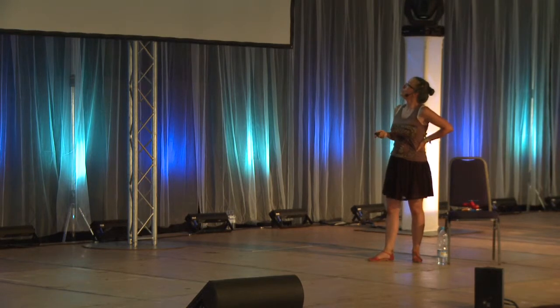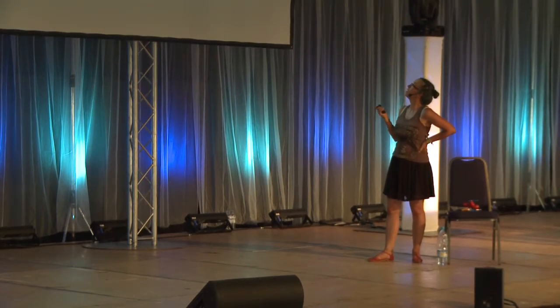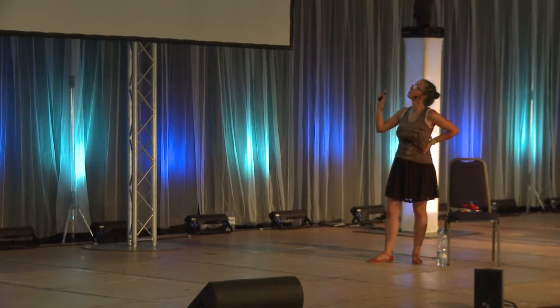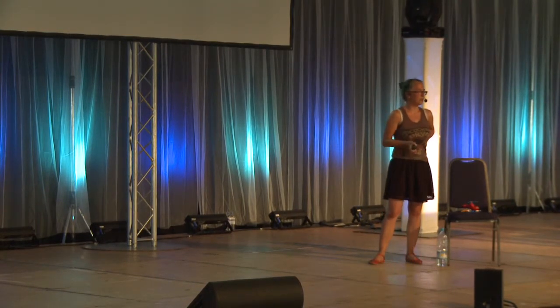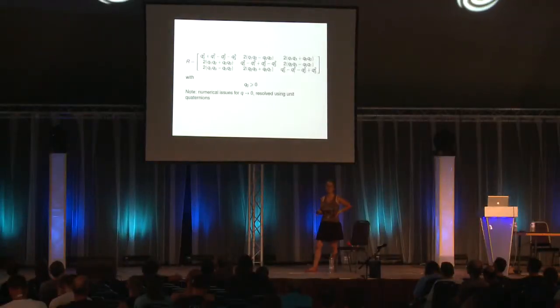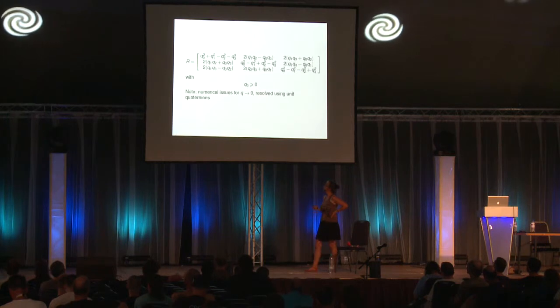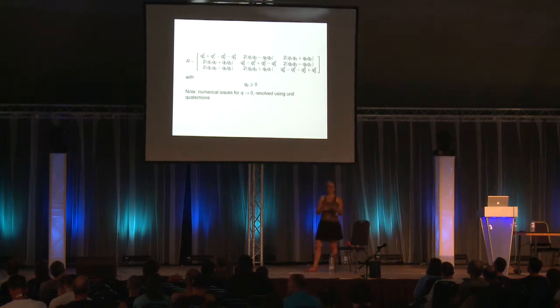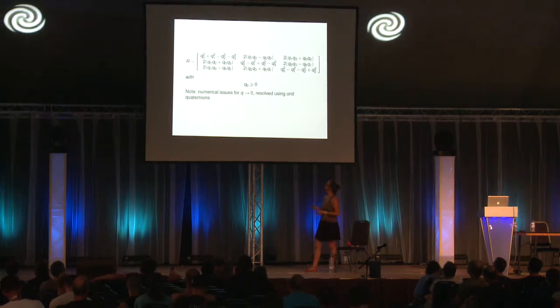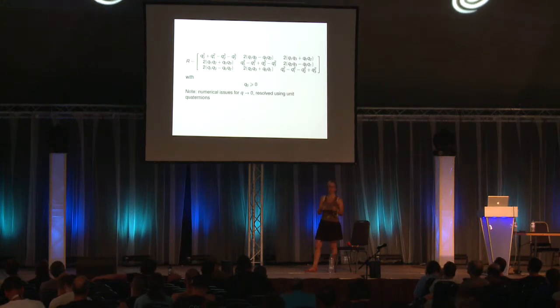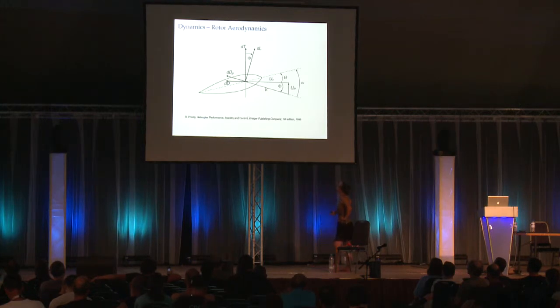And what you do now is you obtain your rotational matrix. It looks a bit complicated. You don't have to keep in mind all these entries. If there's a numerical issue, which could appear if one of these quaternions is going towards 0, you can just choose the maximum of solutions because you have 4 quaternions for 3 positions, and the rotation matrix is an orthogonal matrix, so you also have some redundancies in the entries of the matrix. So it's a pretty nice approach, solving every problem with the rotational matrix, but it doesn't look that nice. So we can come to rotor aerodynamics now.